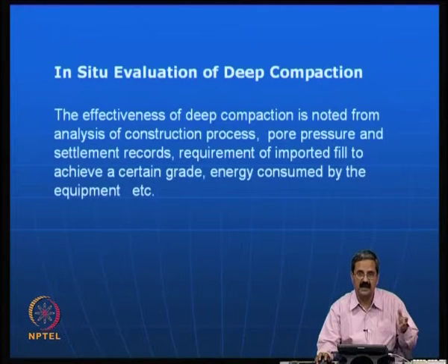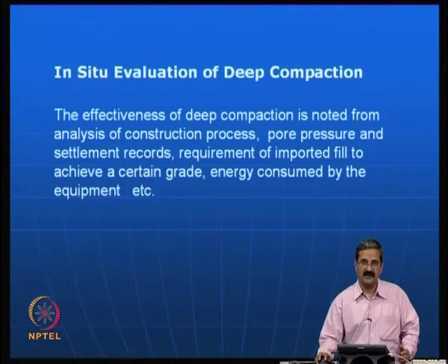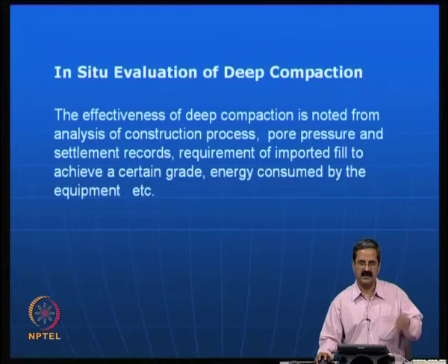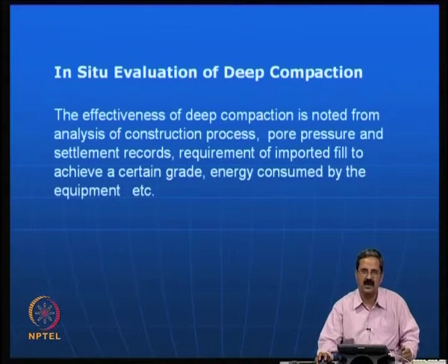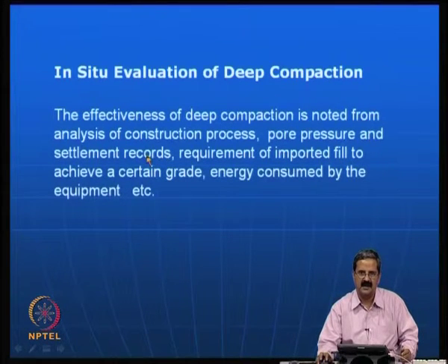Also, say for example, if there is a problem of noise because of the deep compaction, you can even go for smaller heights and closer spacing. One can always work out some processes wherein you can still get the effective improvement.